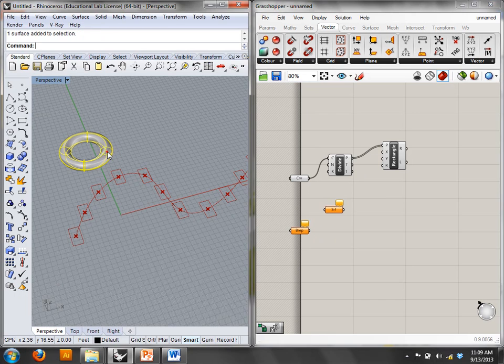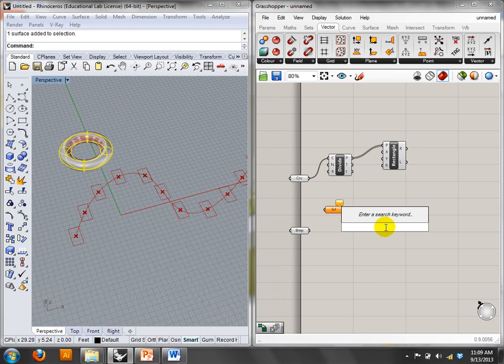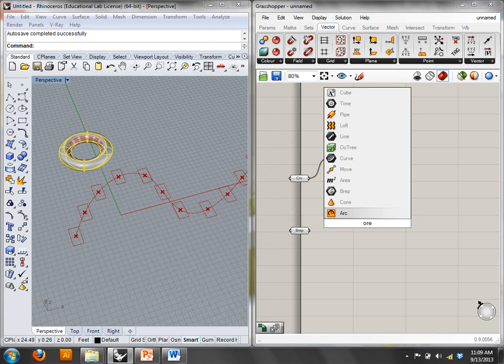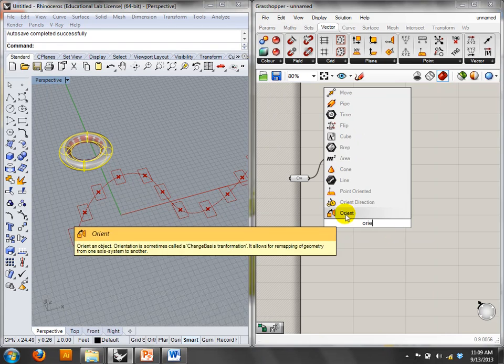I can take any geometry I make. I can make a 20-story skyscraper, and I can reference it as a B-rep if I want to. So I take that B-rep and reference it, set one B-rep. Then I've got points, but I don't have anything I can plug into that just says distribute it. What I can do is orient that B-rep.